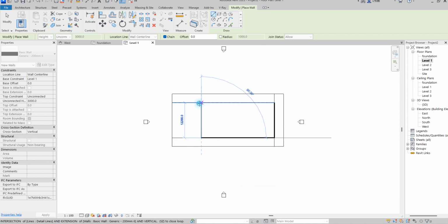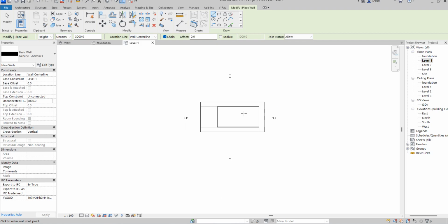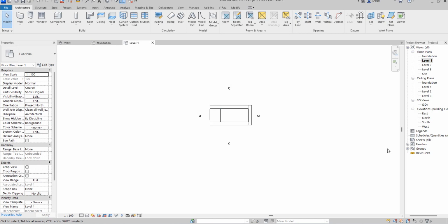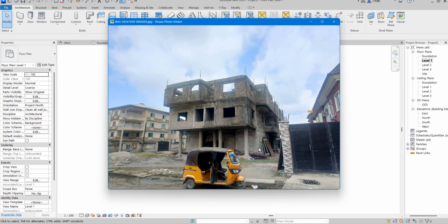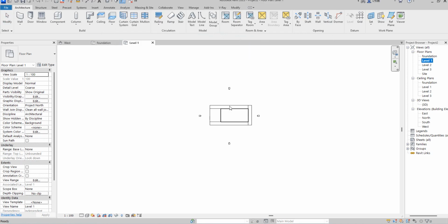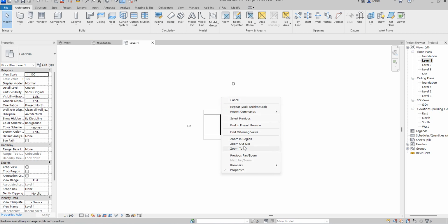Then I have this one. I just like drawing the box first, then I proceed. So what I need to do is that according to the measurement, the house is divided into something. So when you look at it from here, you see that you have a pillar at the front, which are those things you need to take into consideration whenever you are doing your design. So that is the existence. So I have to do that. I measure that one. The whole length of the building is around 26 meters. So that is what I'm going to use.